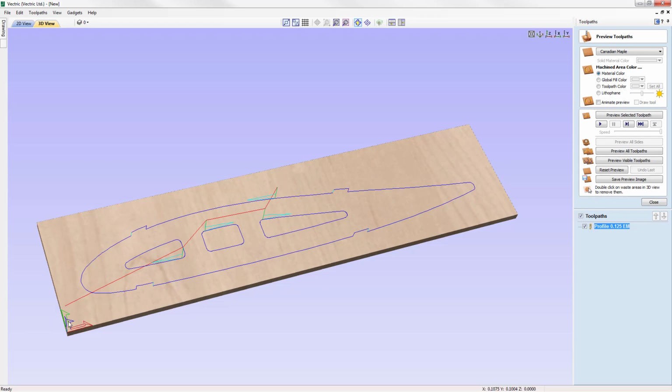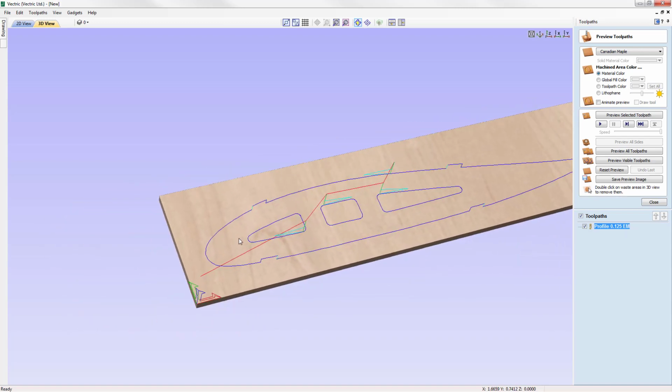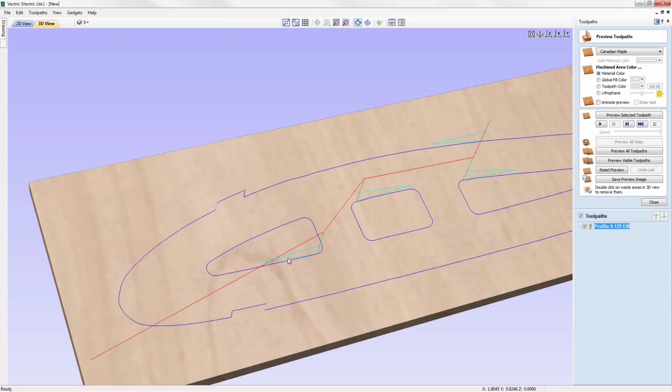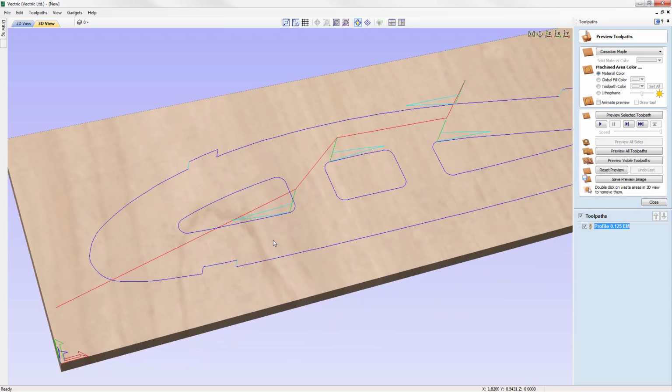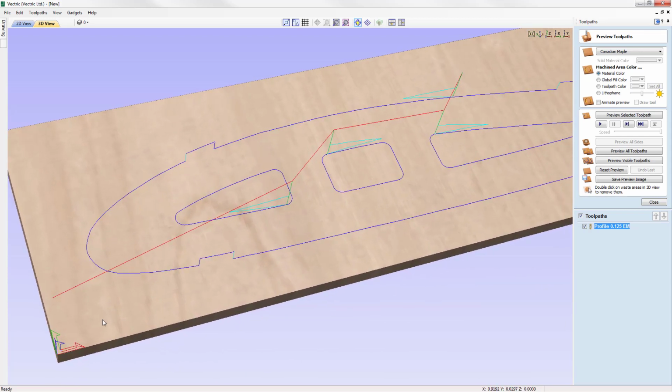Over here, these arrows represent our origin, our X0, Y0 position. If I use Control and hold down the left mouse key, I'm able to pan my material, and then using the scroller of my mouse, scrolling that away from me, I'm able to zoom in to our part.